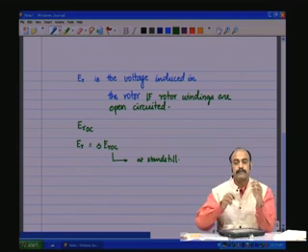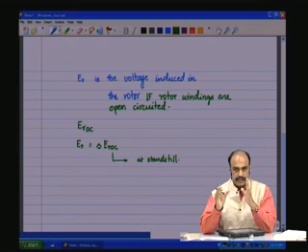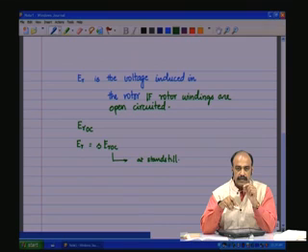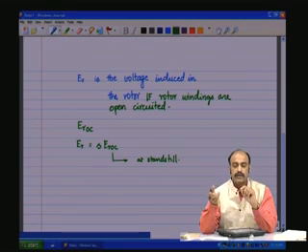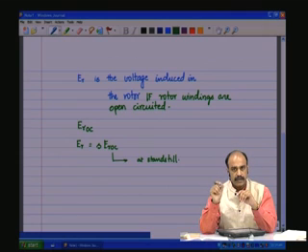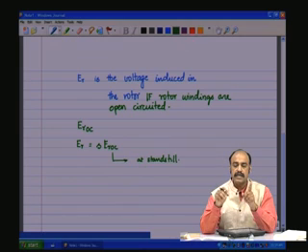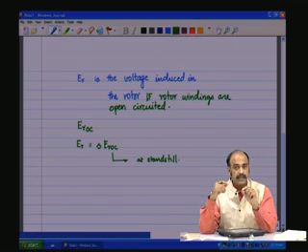And what about the frequency? When the rotor is at standstill, the rotating magnetic field has a frequency of, let us say, omega s. Then the relative speed is also omega s, and then the induced currents in the rotor has a frequency of omega s. Now as the rotor is catching up with the rotating field, let us say it is rotating at omega m, but the relative difference in speed is only omega s minus omega m, and therefore the currents in the rotor will have that frequency, which is omega s minus omega m.